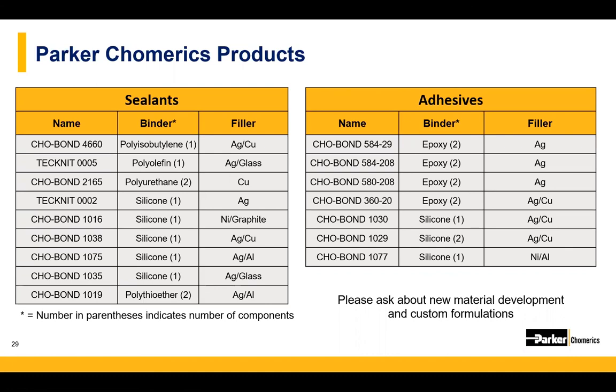A question from Todd refers to hermetic modules and hermetic sealing. When not within a hermetic enclosure, some of the products are exposed to terrible conditions like salt fog, jet fuel, low pressures, high temperature swings, vibration, and a 30-year lifetime. Are there any suggestions for keeping RF covers in place? So I guess in that case, we would look at potentially combining conductive compounds with some of the other conductive solutions.